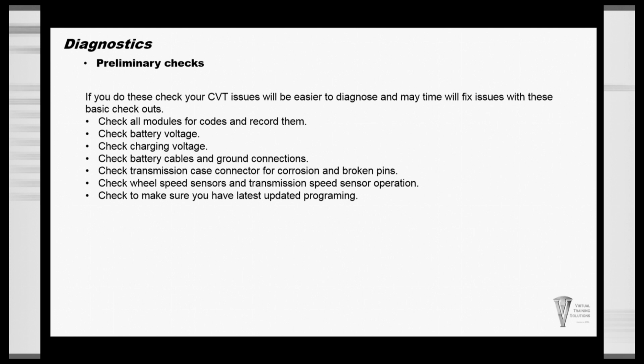We have seen some major problems where these vehicles run at 9.5 volts, start just fine, and have no shifting problems. The ratio wouldn't change. We've had engagement issues, no acceleration, or no throttle pedal, all just because of bad batteries.